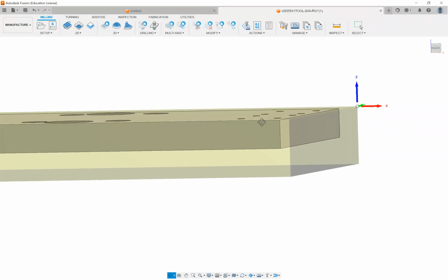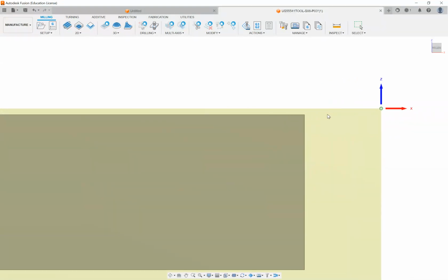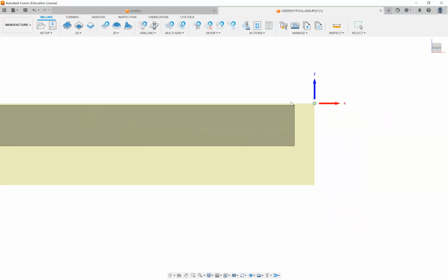And you can see now, if I go look at the side, we've got enough on the very top surface to skim flat, in case we have stock that's not really accurate, we can take a skim cut. And then on the bottom area here, this stock we'll use to hold on to in our jaws. And then our finished piece can stick above the jaws, obviously, so we don't run into the jaws with our end mills and other tooling.